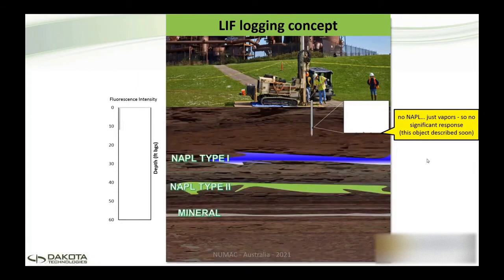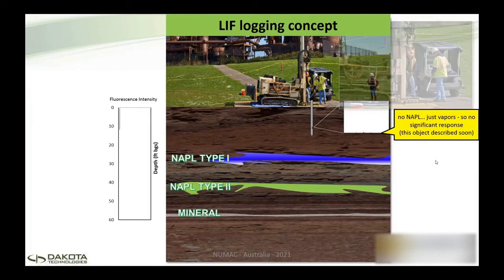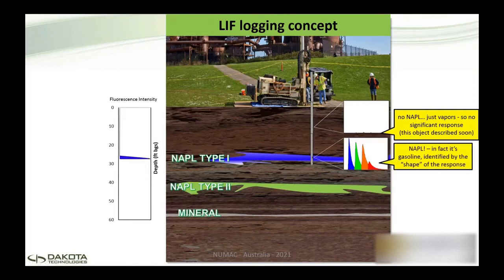Okay, well, they screw another rod on, right? He runs the rod across the fiber optics. He screws that into place, and the geoprobe slowly taps that probe down into the soil, and wow, okay, we've all of a sudden gotten into some soil that generates a large fluorescence waveform, is what these are called. And we know it's NAPL. And by the shape, just by the shape of these 4 peaks, I can tell you that it's gasoline, or it's something that looks exactly like gasoline.